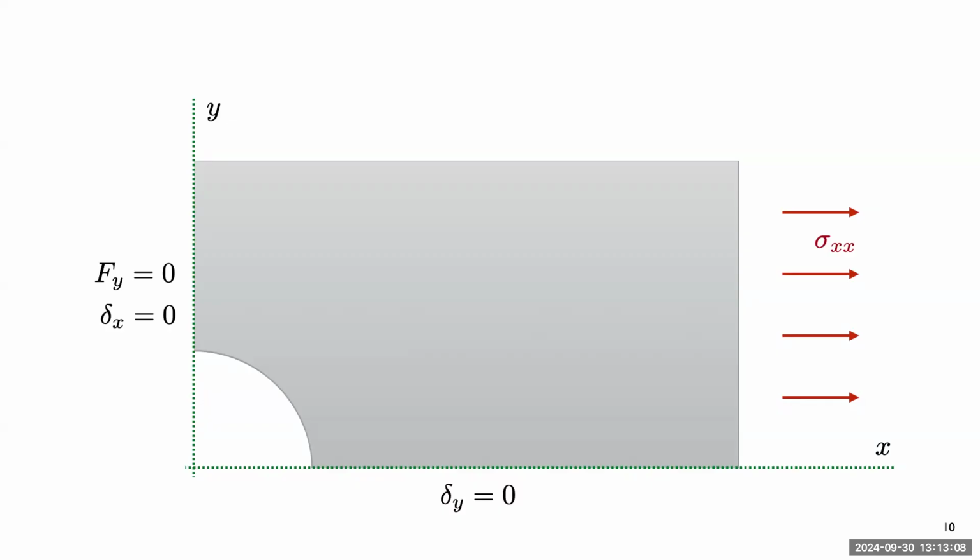In a 3D problem, the force in the z direction will be 0 as well. And equally, you can say that at this plane here. A symmetry plane, you can think of it as if you had a perfect bearing, say a planar roller bearing that was adhered to the table, and you were holding a plate on that. If you try to pull against it, it won't let the bearing move away, but it'll have no resistance to moving along the table. So that's all a mathematical symmetry plane is doing.